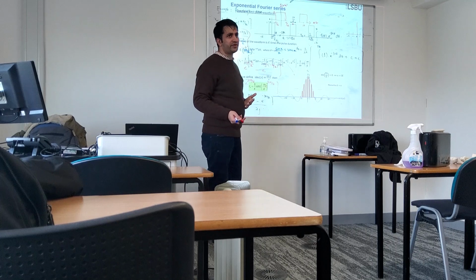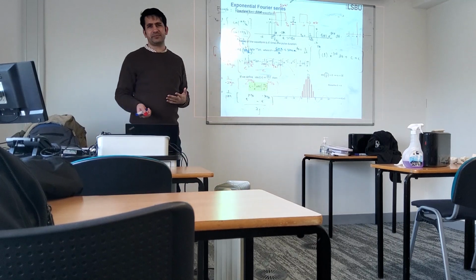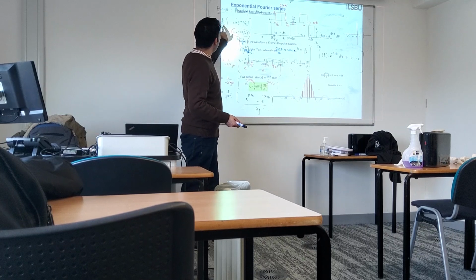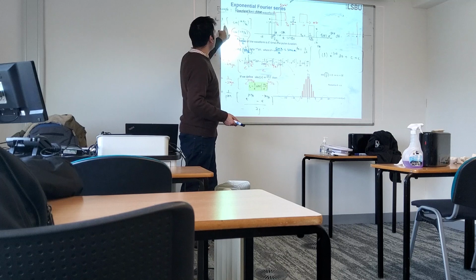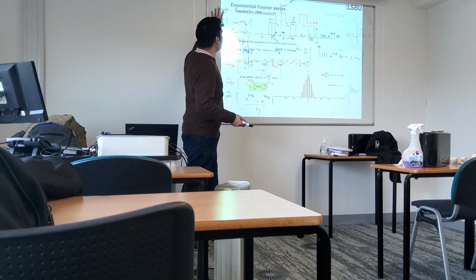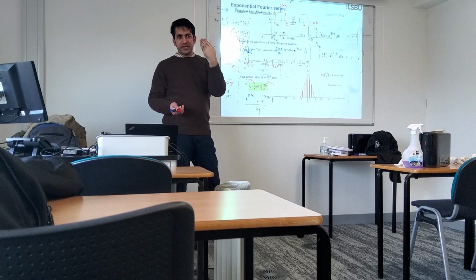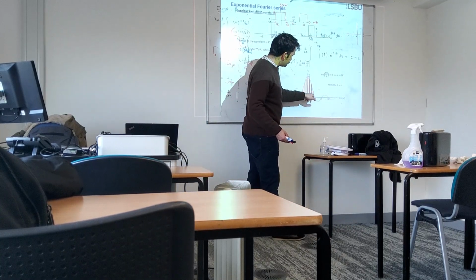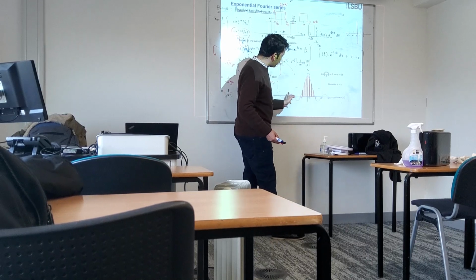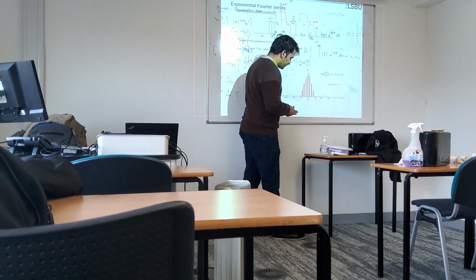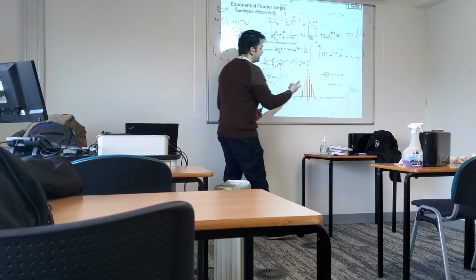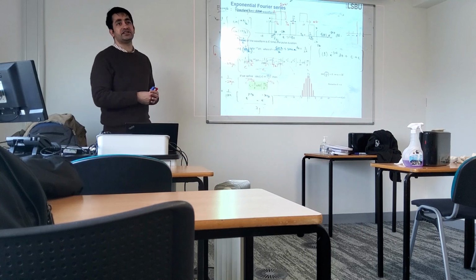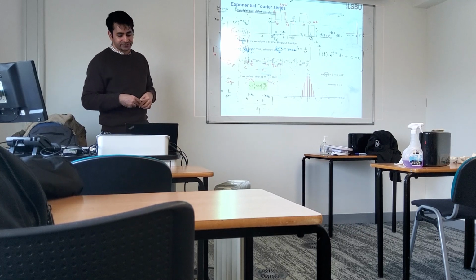We can solve the sinc function using a calculator, but normally sine is easy to solve. So if you put n equals 1 and k equals 4, you will get one single number. Then you put n equals 2, you will get another single number. This is drawn with respect to n. You can see the spikes, but if we draw a rough sketch over them, they look like a sinc function. So the coefficients are a sinc function.